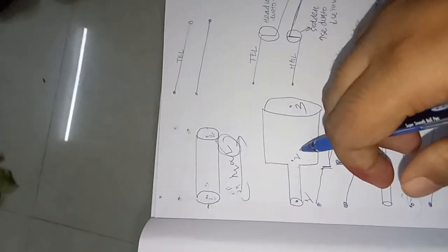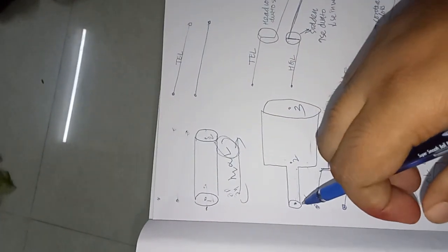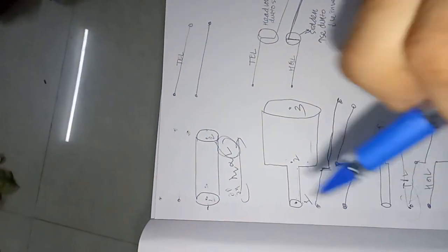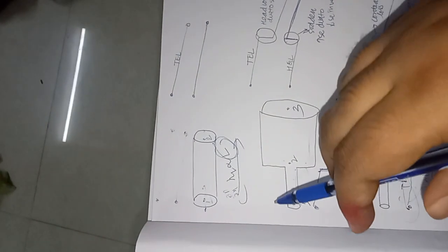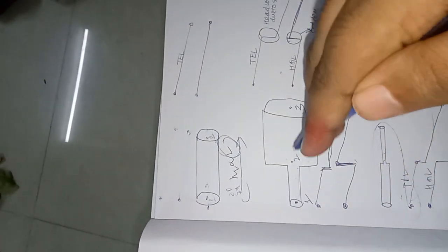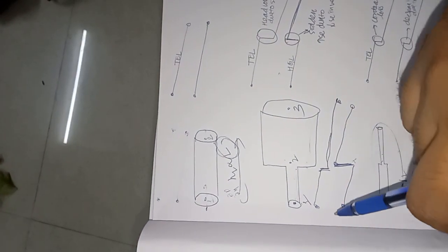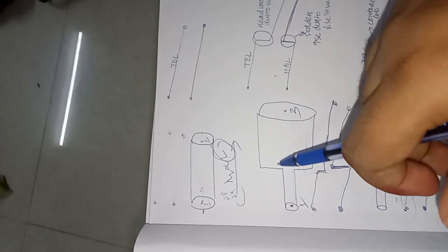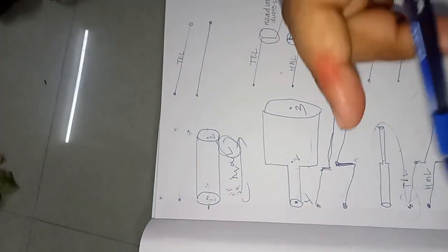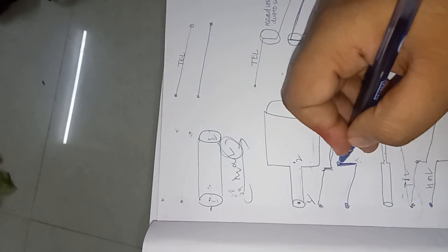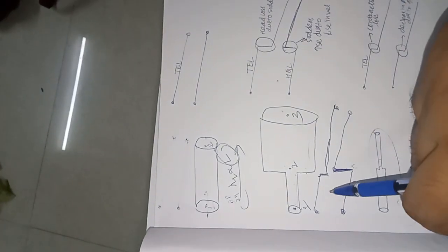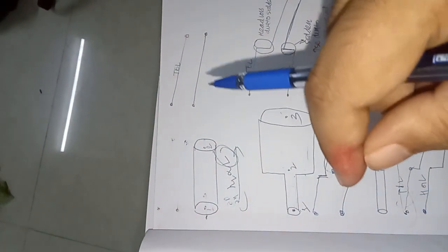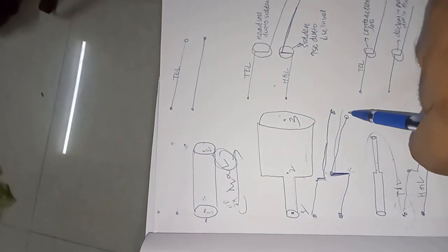Second case, sudden expansion. Sudden expansion, points 1, 2, 3, from the hydraulic gradient line. From here to here, pressure decreases. Z is constant everywhere, so the hydraulic gradient line depends only on pressure. From here to here, pressure is decreasing linearly. Now, due to sudden expansion, the velocity suddenly decreases, which means pressure suddenly increases. So the hydraulic gradient line has a sudden spike, and then again, due to dP by dx equal to minus constant, the pressure decreases.